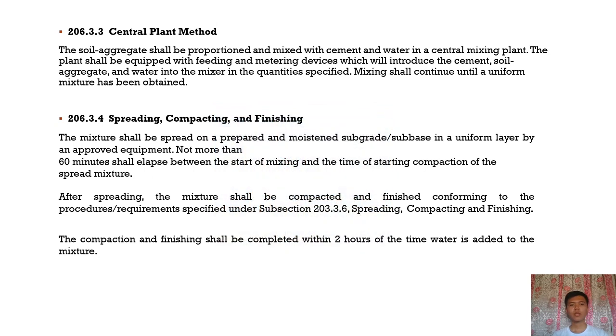Next is spreading, compacting, and finishing. The mixtures shall be spread on a prepared and moistened subgrade or subbase in a uniform layer by an approved equipment. Not more than 60 minutes shall elapse between the start of mixing and the time of starting compaction of the spread mixture.